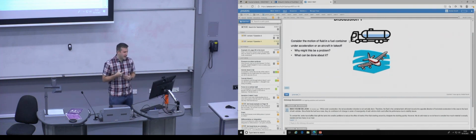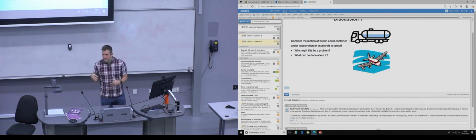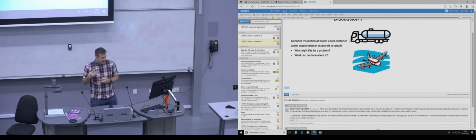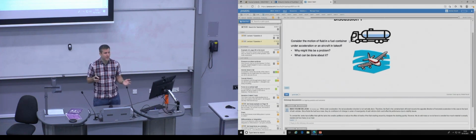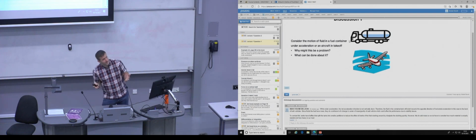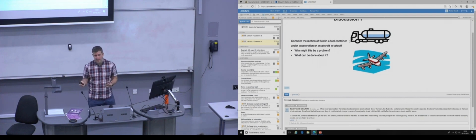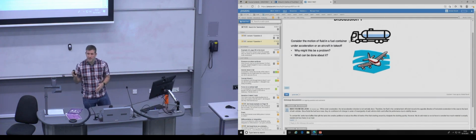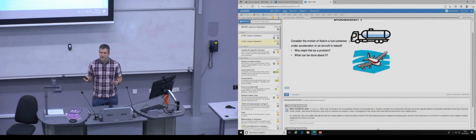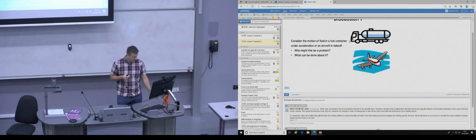So basically, we've got this quite large mass. Remember, fuels in an aircraft can be a significant proportion of the mass in it, right? In a space rocket, you're talking about maybe 90+% of the mass of the vehicle on the launch pad is fuel. I mean, that's a special case, and in a space rocket, you're not doing a lot of complicated maneuvers. But when you have a lot of fuel, you have to work out how to control it when it's being maneuvered. And this is a classic problem with fluids.